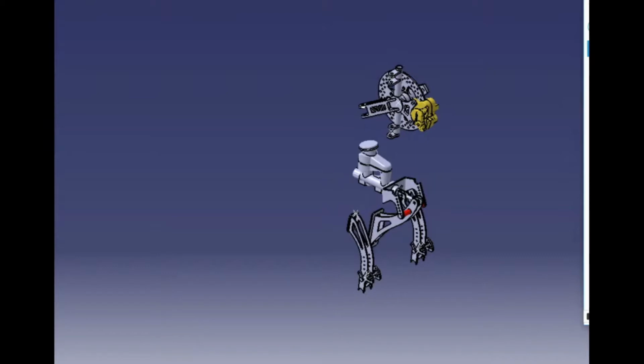So to find the force on the master cylinder, we have to first calculate the force which the driver creates on the brake pedal, which is multiplied and sent forward with the help of a pedal ratio. To get the idea of how this works, first the driver pushes the pedal, creating force on it, which gets transferred to the master cylinder and hence to the caliper piston. Here, pedal ratio is the mechanical advantage given to the pedal, which multiplies the pedal force given by the driver.